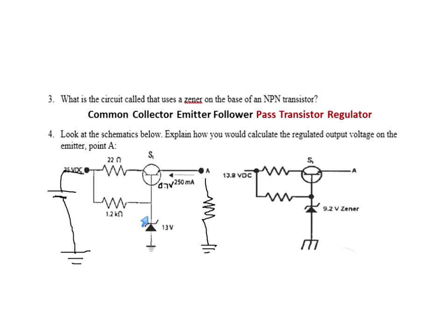What is the voltage on the base? Because remember, the basic purpose of a zener is to limit its reverse bias voltage to the voltage of the zener. It's going to conduct to allow what voltage right here? Not 25. What voltage is going to appear right here? This 13. I'm going to have 13 volts right there. Right here, 13.